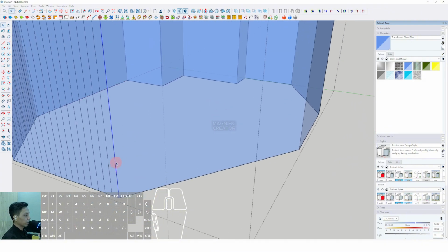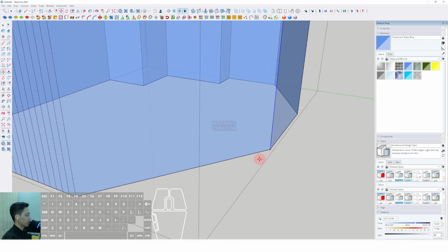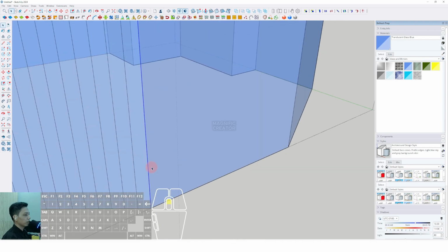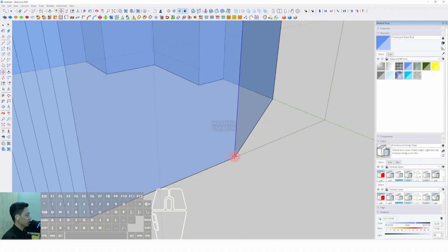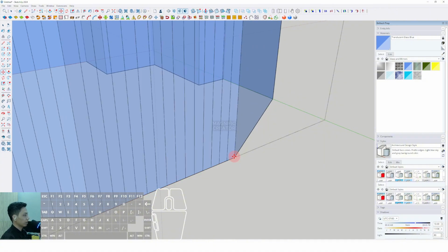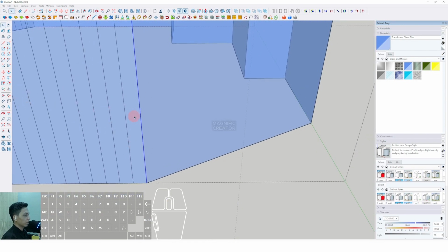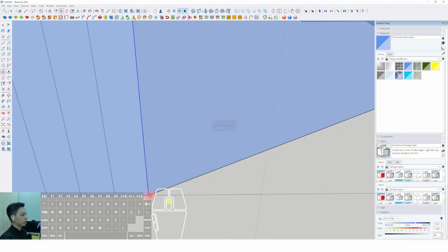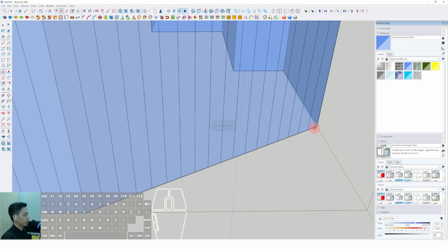Okay, then we can click this line again, select move, press control, place to this position, and then type 27 slash and enter. And this one, select move, press control, click from this point until this point, then type 15 slash and enter. We can click this vertical line and select move, press control, click from this point until this point, then type 18 slash and enter.